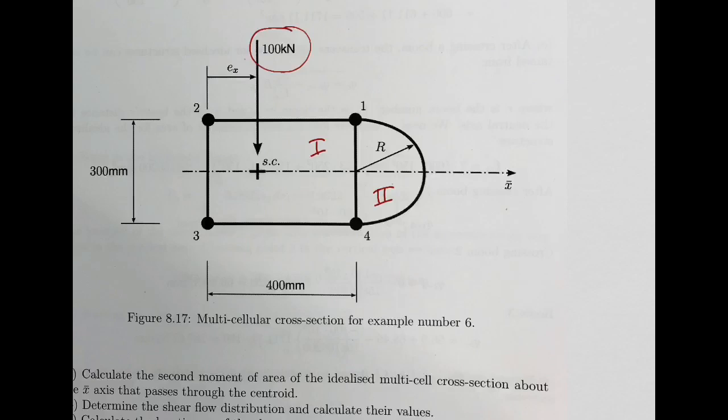So basically the shear center is the location in the cross-section where, if you have the lift, for example, in a wing, applied at that point, at that shear center, it means the cross-section will not rotate, will not twist. It's a very important point because we don't want the airfoil or the wing to twist. Because if the wing twists, we lose the aerodynamic performance of the wing, right? We are changing the angle of attack, so we don't want that to happen.